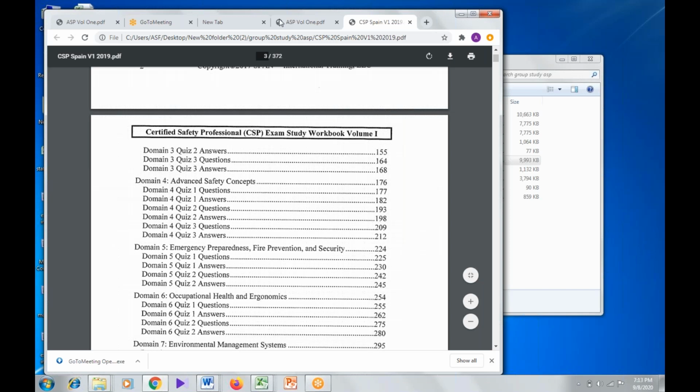If the chlorine exposure is above 2500 pounds for the unit, I think it should be included for both programs, the environmental protection plan and OSHA also. But if it is less than 2,500 pounds per unit, and still more than 1,500, it will be included for OSHA PSM only.